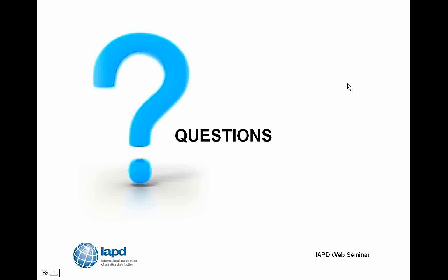I would imagine that that could be easily done by a lab, and there are commercial laboratories who do that as contract work. And there may be an ASTM test with a notched tensile pull. And the website for ASTM is astm.org, and you can explore their tensile test to see if they've got one. The standard tensile test is D638, and then you can look for other tests that are tensile and perhaps have a notch in the specimen.